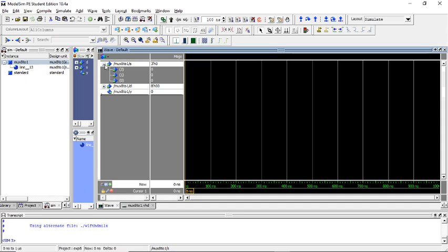So see here, you have two inputs. One is S and the second one is D. S is an array of 3 bits, or a bit vector. So S0, S1 and S2. Based on the S0, S1, S2 value, one of the D values, that is D0 to D7, is selected. Again, D is an array of 8 bits, that is D0, D1, D2, D3, D4, D5, D6, D7, and Y is the output.